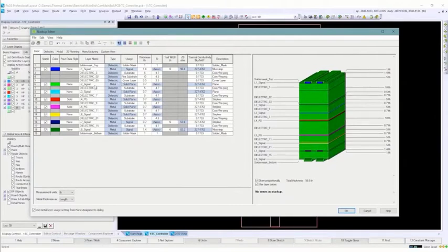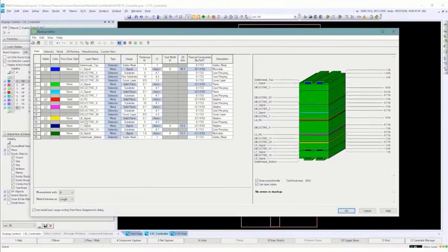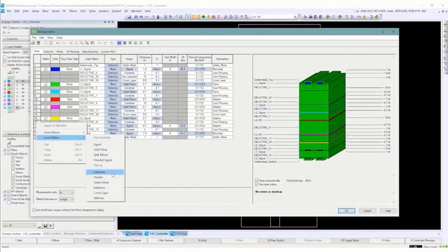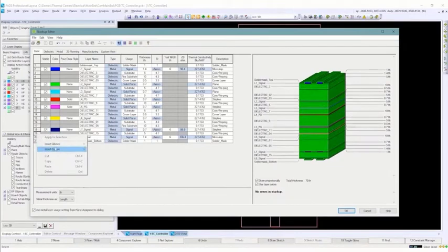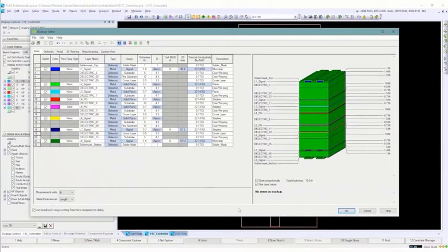And then on the bottom half of the board for the camera and the RF board, we're going to use a 2-layer flex, one with a ground plane on it. So our ground plane is obviously already on layer 6. Just above that, I'm going to add again a cover layer, and then we're going to put a separate substrate in here for the flex. And then we're going to add another cover layer. And then each one of those flexes, the camera and the RF one, are going into flex connectors.